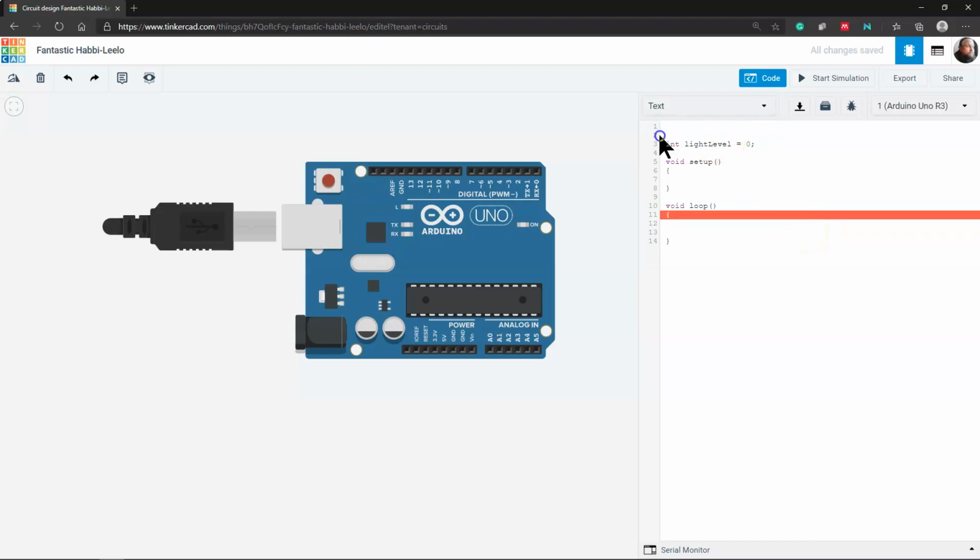And remember again, for anything that's your variables, as soon as we lose power, that information is gone. So once you start it back up, you can't expect that information to be there. You've got to write that to the onboard EEPROM memory, which, don't worry about how to do that now. That'll be in the future of the actual course. Okay, so these are the basics. They'll take practice, and especially for people from Python, I say go through some tutorials, work through some examples, and come back.